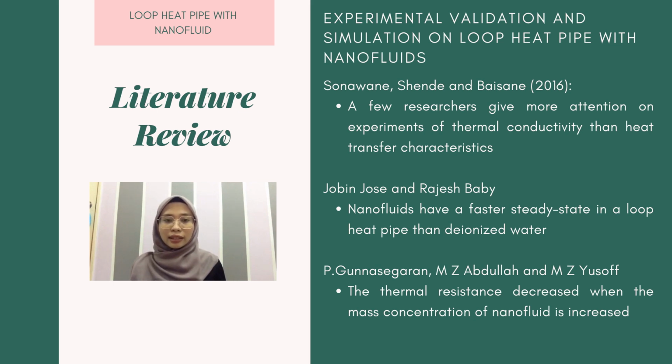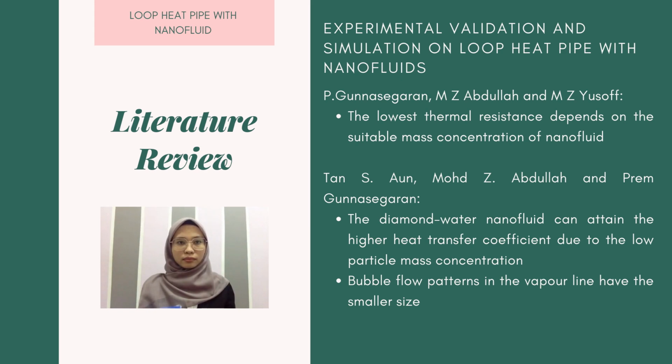Next, the researchers Kanasaran, Abdullah and Yusof developed an experiment to identify the heat transfer characteristic impact of alumina nanoparticles in loop heat pipes. From the result, alumina water nanofluid has a greater thermal performance than pure water. The thermal resistance of the nanofluid also decreases when the mass concentration of the nanofluid is increased. So, the lowest thermal resistance in a loop heat pipe also depends on the suitable mass concentration of nanofluids.